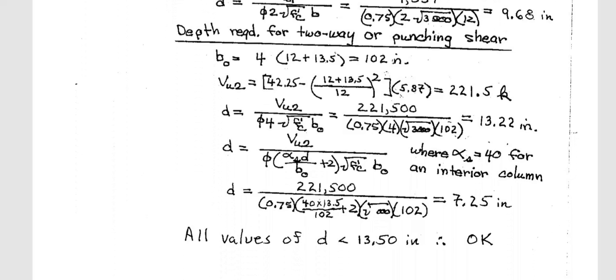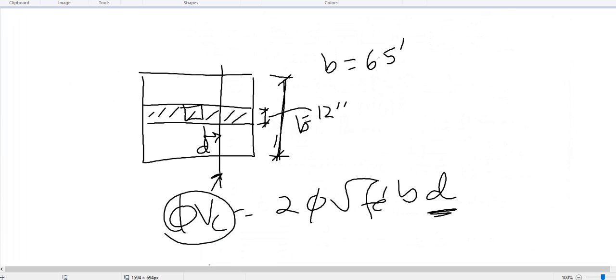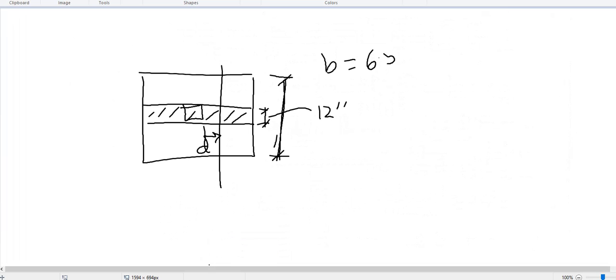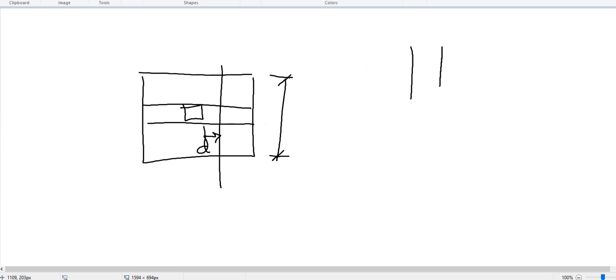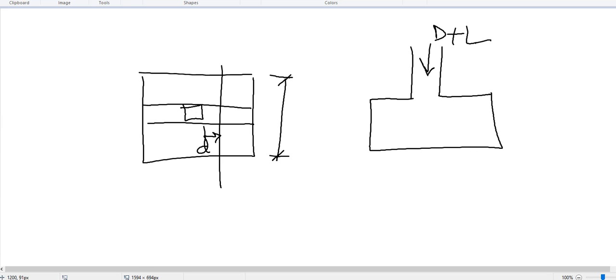square footing. So here is the check for punching shear. Now what is punching shear? Hopefully you know the term punching. Punching means like when you punch a paper, similar to that. That means if my column is here, if my foundation is here, if there's huge load here, dead load plus live load, it may punch your foundation this way. So this part will go up and this part may go down.